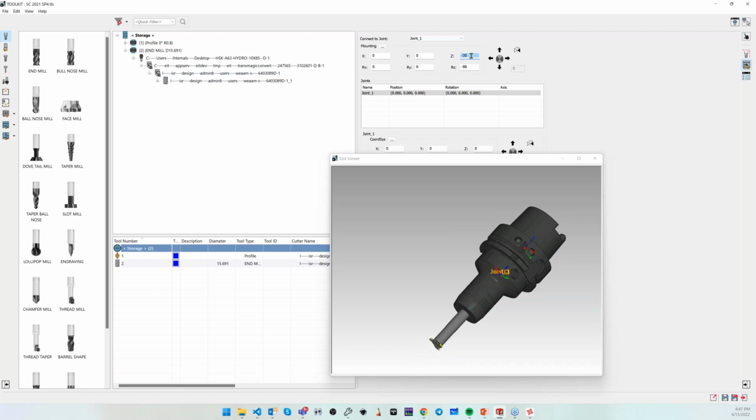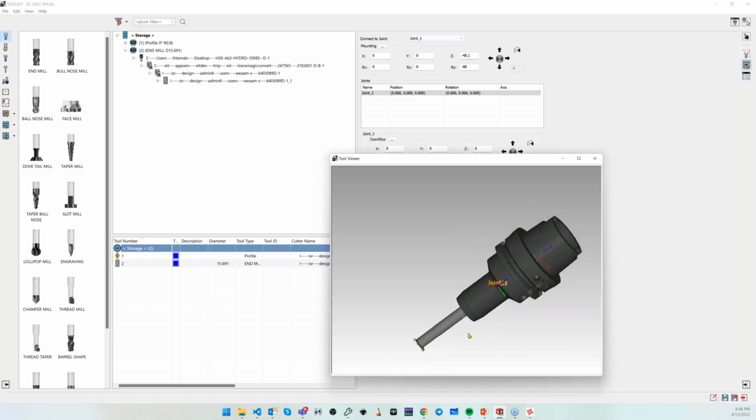You can just roll your mouse here and use the Shift or Control keys to change the precision of movement. When you press the Control key, it moves 100 millimeters as you scroll. If you press the Shift key, it moves 10 millimeters. Without it, just by mouse, it moves every millimeter. And if you use Control and Shift, I think it uses 0.1 millimeter. So you have all options to change this value dynamically. And yes, you can change the extension of an imported tool without any problem.